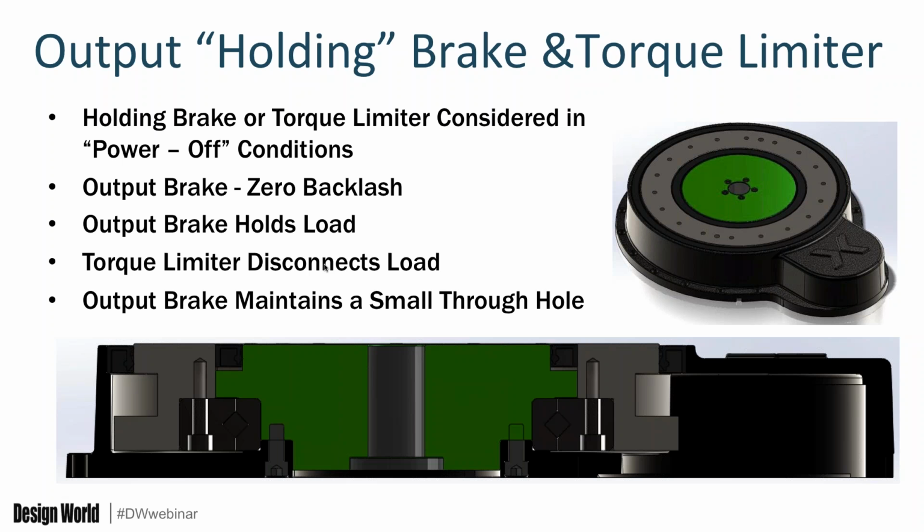And what happens is, if you have a situation where torque is exceeded, power off condition, a jam, the clutch will actually free itself from the detents and disengage from the power source. Now what that does though is the output inertia is freewheeling, and so you're still moving at the output.